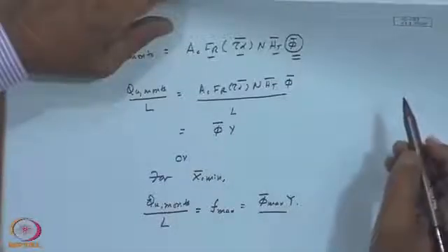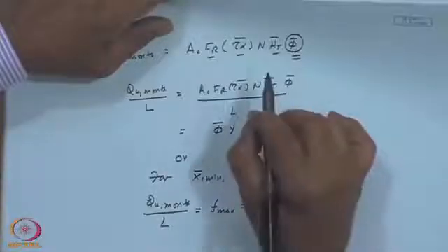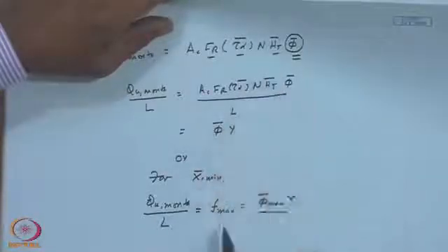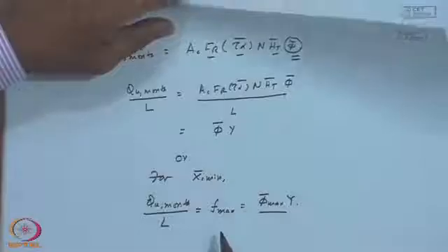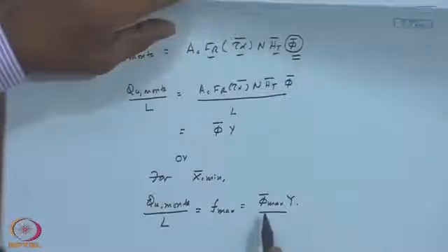If all the energy delivered by the solar collector is going to meet the load, there are no losses in the pipelines, there are no losses in the heat exchanger or in the tank, then this will be the solar load fraction that will be met. So, in one sense, simple knowledge of utilizability can give you an estimate of what is the possible maximum solar load fraction.